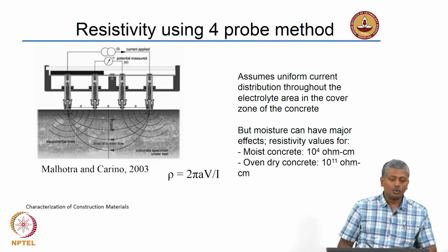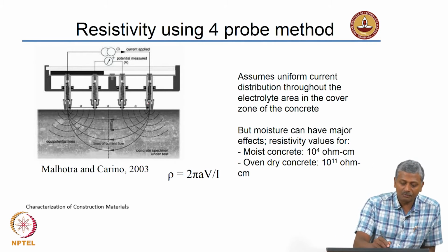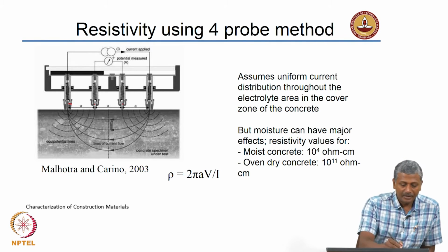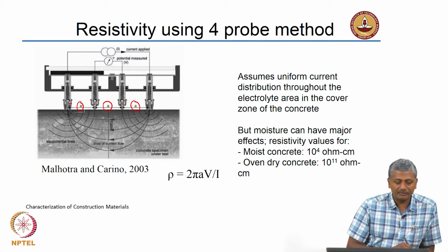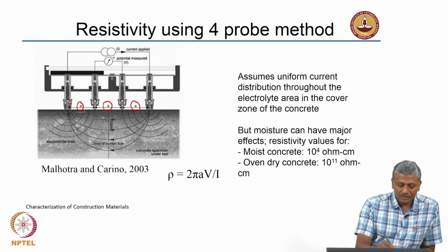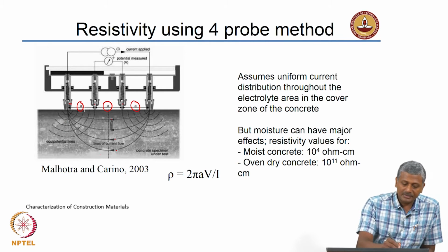If you look at the more detailed drawing of this resistivity, again these are the 4 probes that are sitting directly in contact with the surface. The distance between the probes is constant, A. In all the cases you have the constant distance between the probes A. Now, if you look at the lines of current flow, they are defined by these isopleths that are drawn in this figure. However, the equipotential lines are what are emanating from the source of the current.